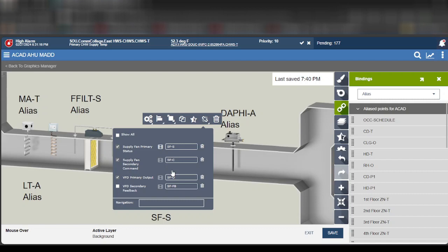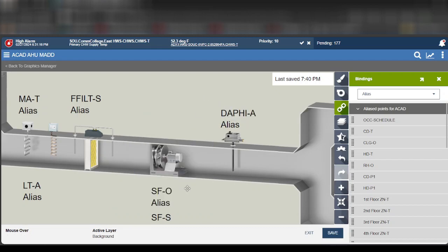Particularly if you are working with older systems. We literally have 30-year-old DX9100s out there in some of our buildings that we have not replaced yet. The naming conventions and things like that do not work. They will not fall in place, so you do have to go in and manually add these particular points. For example, what I would do here is I would simply go over, grab whatever point that I needed, such as a supply fan command from my list, and just drag it in here as you had seen me do earlier. Okay, very simple process.